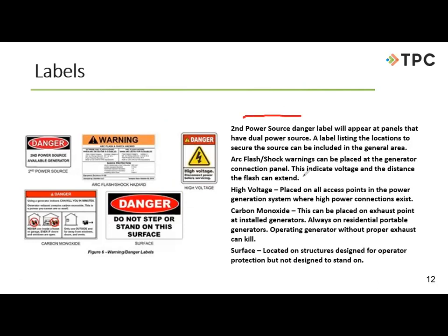Could also have an arc flash warning label on here. It's definitely going to need a shock hazard label, because if we are above 50 volts, we do have to let people know that there is going to be a shock hazard there.